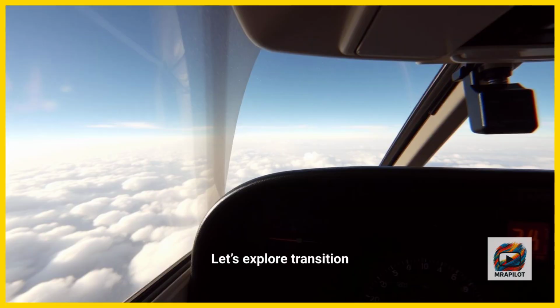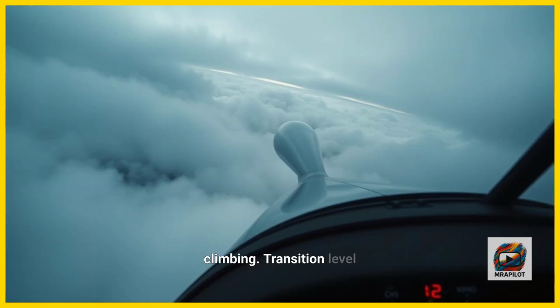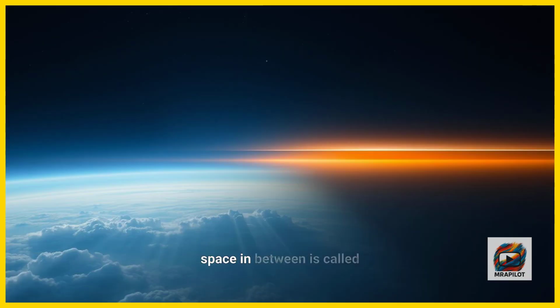Let's explore transition altitude versus transition level. Transition altitude is the point where you switch from local QNH to standard pressure when climbing. Transition level is where you switch back to QNH when descending. The space in between is called the transition layer.